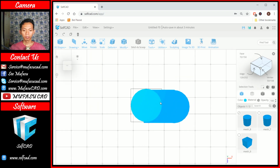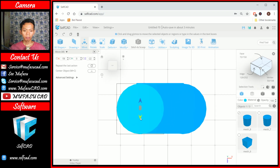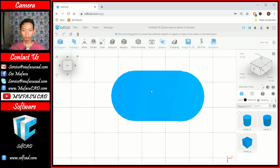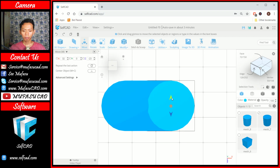Okay, you can zoom in. And then I will move this cylinder object to the bottom here, and you can move to the left this cylinder object in right axis, and move again to the bottom here. Okay, I will click at this cylinder object, and then I will move to the top, this point. Sorry, we can change into top view and select this cylinder object, use move tools and move to this point.